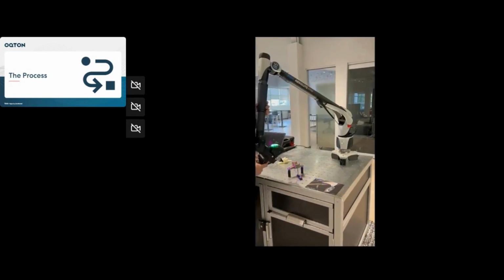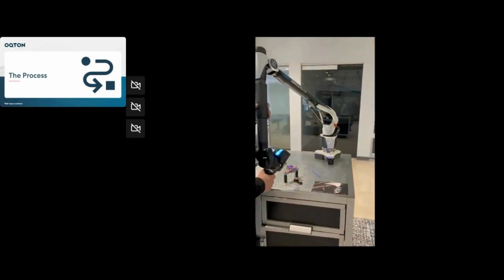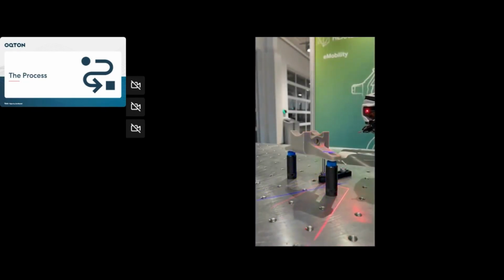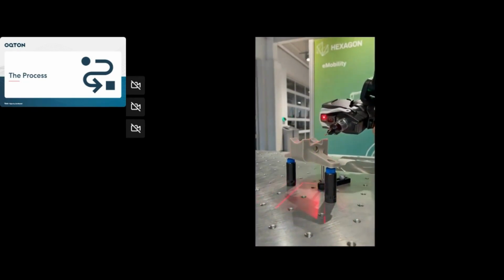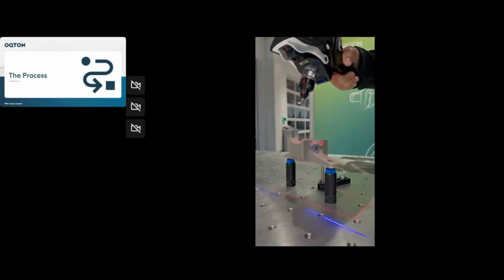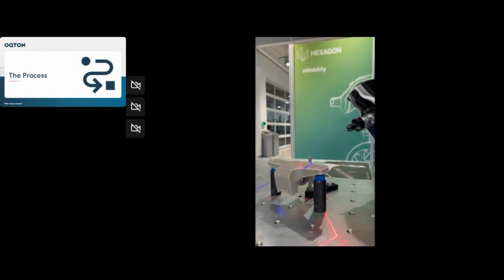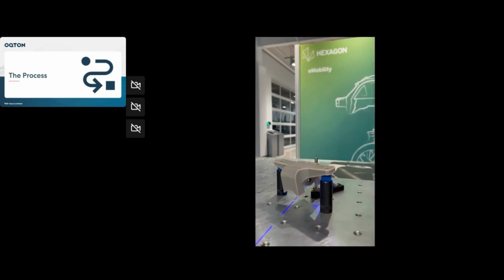Yeah, the scanner moves so fast, it actually took me longer to get here and back with traffic than it did to do the process. So what we're showing on the screen is you take the part, you elevate it, you scan one side of it, then you flip it over, scan the other one, and you mesh the data together, and now you've got a digital twin. That lives in the point cloud. And that data, we take and clean it up, and then you feed it back into Design X.